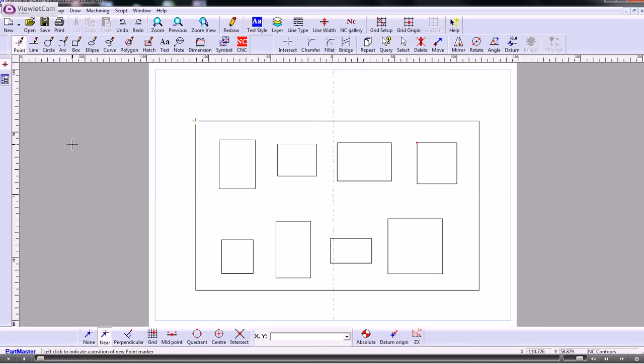In this video we'll show you how we can handle multiple cavities in the wire EDM software. So I've created a simple drawing. Across the top we've got 4 cavities which will machine as individual cavities, and therefore there'll be a wire break and a wire rethread sequence required between each cavity, and across the bottom we'll turn that into one continuous path.